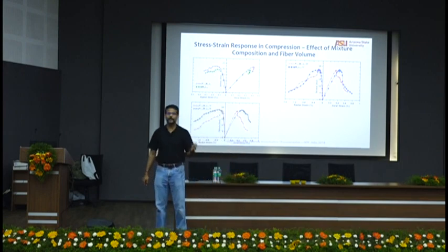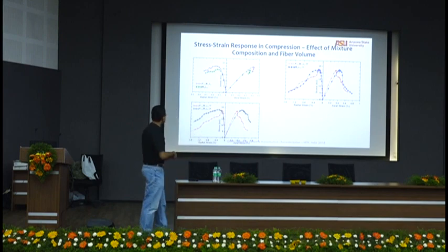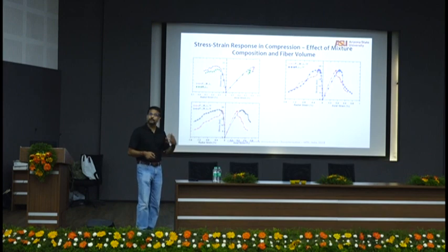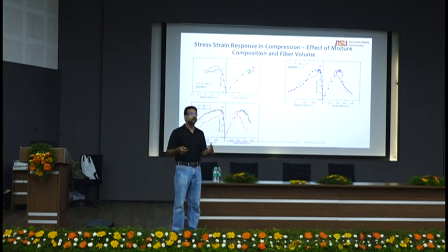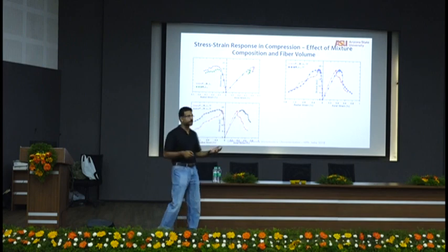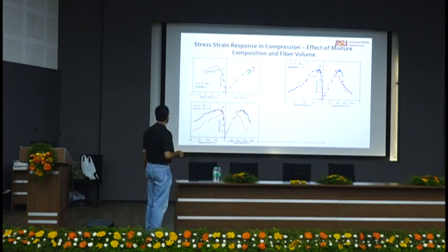So we use only 0.3% or 0.35%. Even if you want to use the maximum usable compressive strain, you still are okay for design. But because of the very high strength, you would not want to get to 0.3. You would want to stop at a much lower strain, probably 0.25 or so, and that's fairly good.